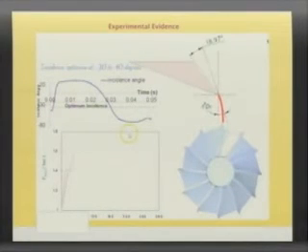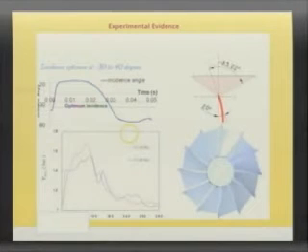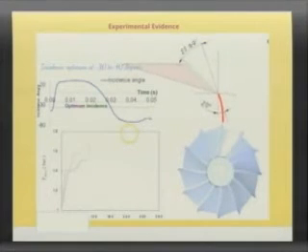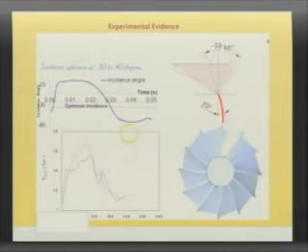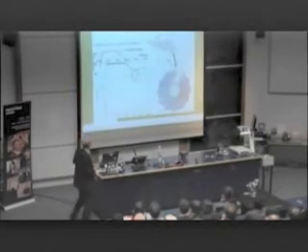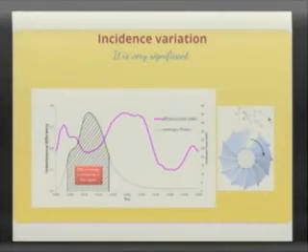During the pulse, it is moving to the left, plus 32, plus 28, precisely when I have most energy. And it turns into minus for a minor period of time. So these guys really have made an entire mess of my turbine design, because it is being pulsed to such an extreme that you're bound to get what we call flow separations, and we show you a very brief picture of that. So you see the energy was here in the pulse.